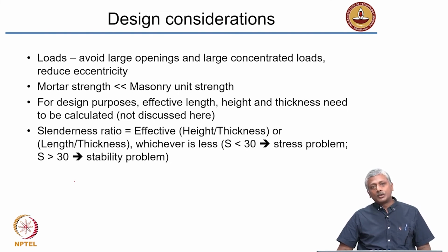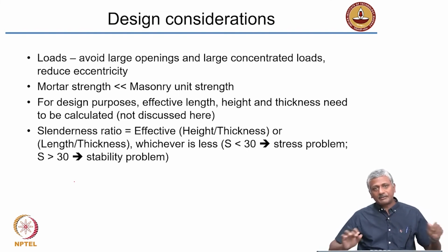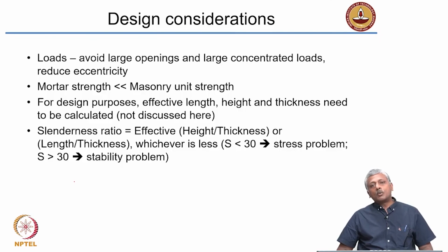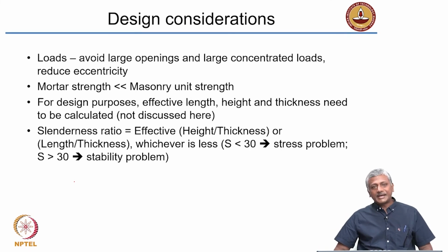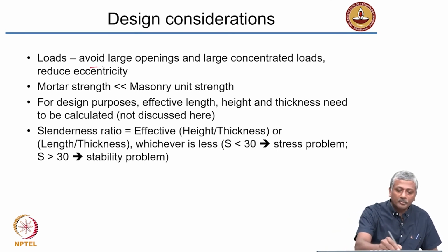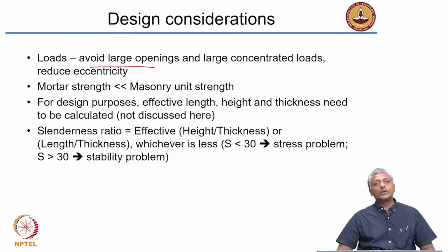So, to ensure that the load distribution is uniformly given to the foundation, we want to avoid any concentrated loads coming onto the walls, because concentrated loads cannot be taken effectively by walls. They need to have well distributed loads. Secondly, we want to avoid large openings.